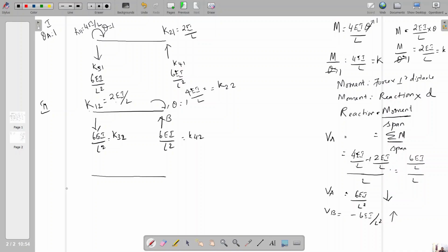Next one, the third subdivision, you apply here unit displacement, because up to this step we are considering unit rotation, because it is a moment. It is a moment, so we can apply only unit rotation. Here it is a force. So the moment is related with theta and force is related with the deflection. So you apply a unit deflection here, delta equal to 1.